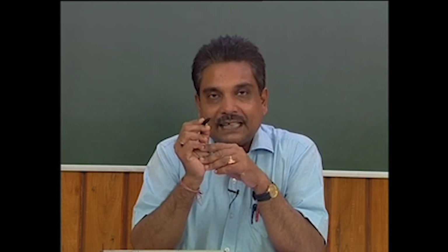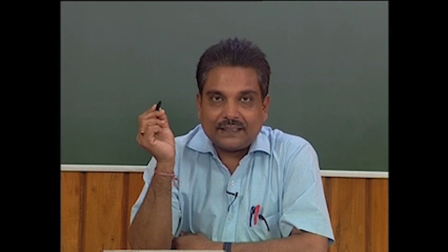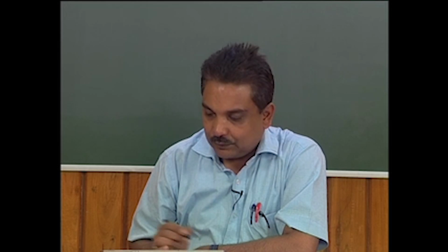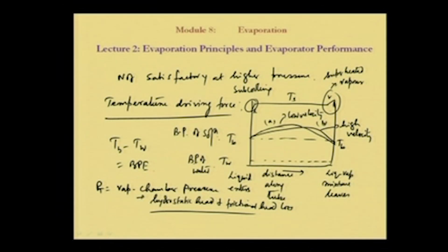Now, many a time it need not be a single effect; there can be multiple effects. Before I tell about that, one thing I should say here is that the vapor comes in a little bit superheated, not exactly saturated, because if there is some heat loss, it will be condensed prematurely. So some amount of superheat is needed, and while going out of the heat exchanger, a little bit of subcooling is possible.